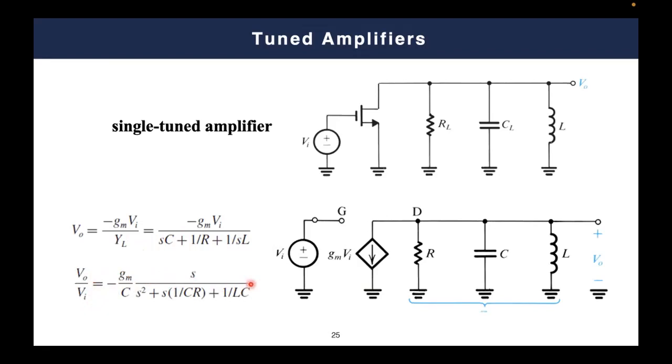The new thing here, with respect to what we already understand from our electronics 1 and electronics 2 classes, is that usually in such circuits, our loads are in the form of a resistive load, RL and all these things. But now we have an RLC network in our load. That's why we have this S domain function, and it is a second order S domain function.